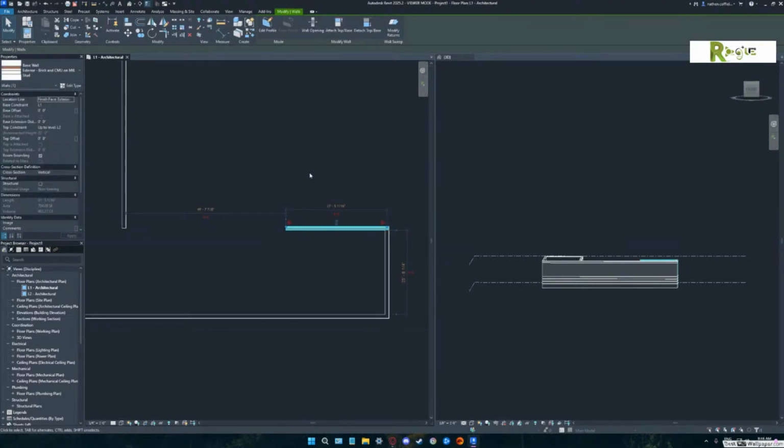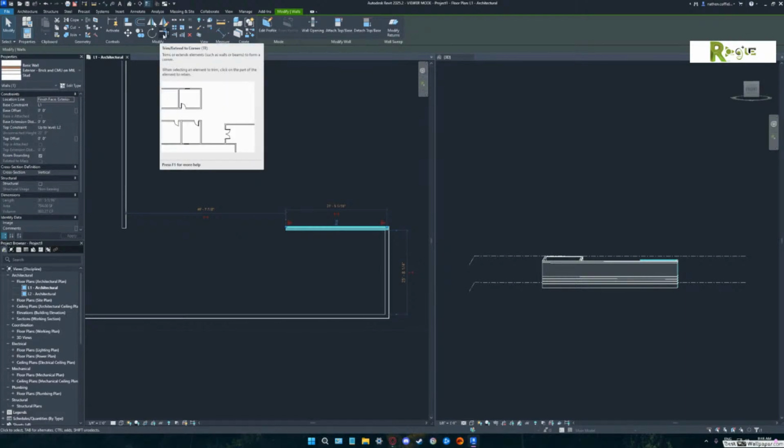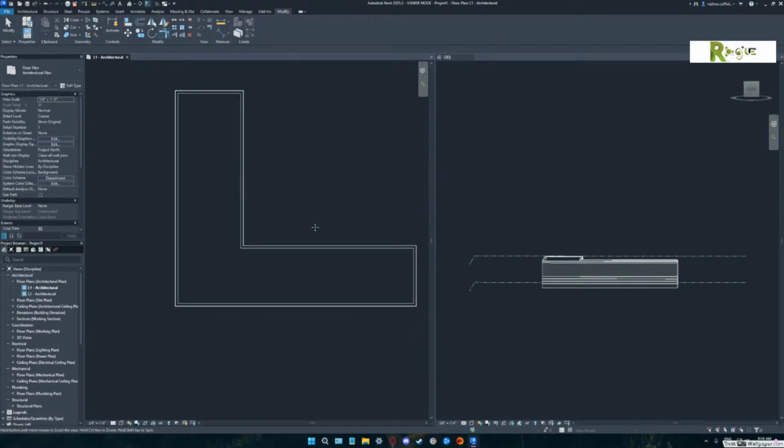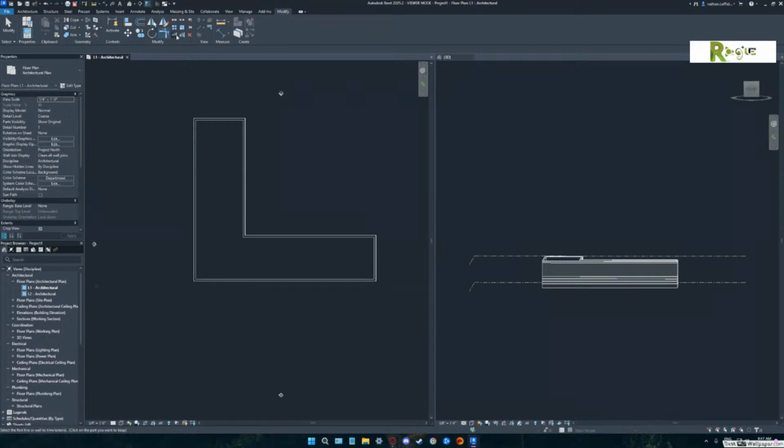There is a miter command. It's right about in the middle of the commands at the top. Now go over towards the middle of the modify tool pan. Down a little from where you were. That one right there. That's the trim and extend, or most people from AutoCAD would call it the fillet or the chamfer. And then what that allows you to do is to pick those 2 walls and join them together. And right next to it is the one that does trim and just trims one line. And then the multi-trim is right there.